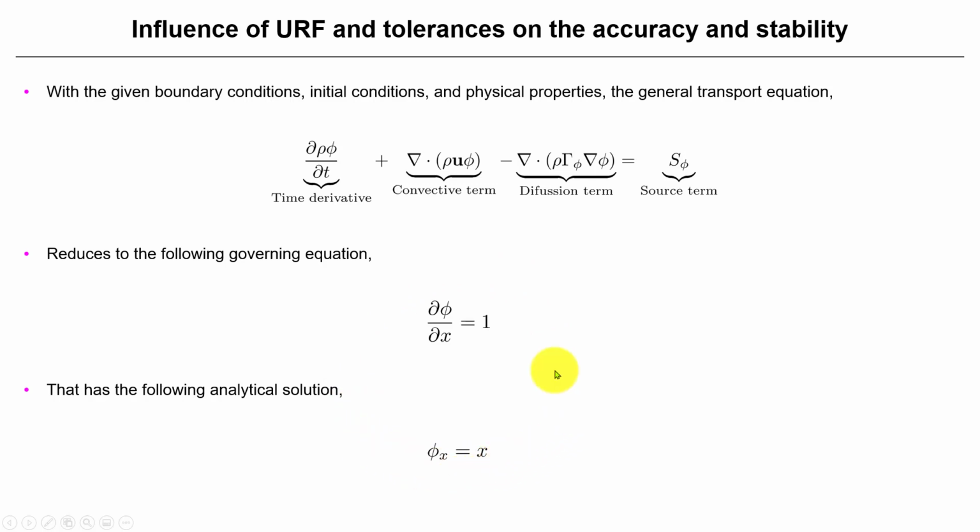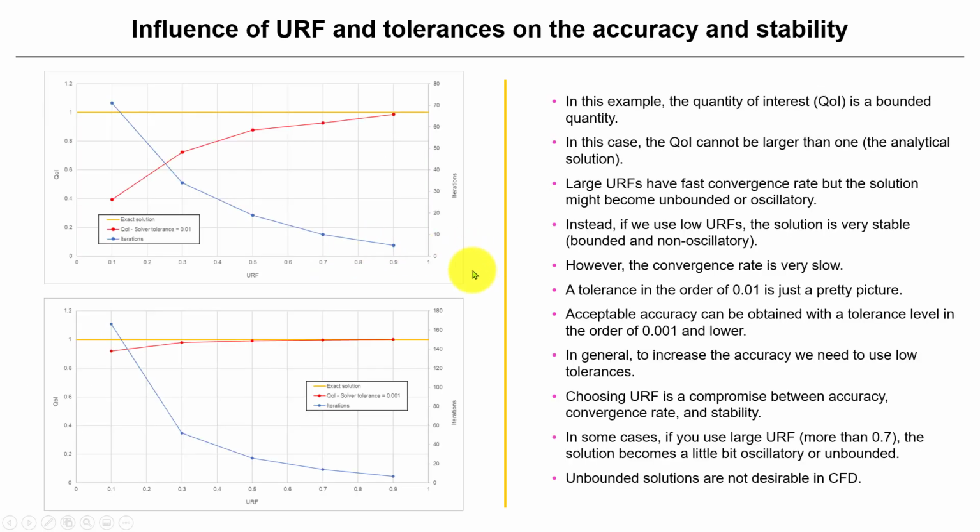Here we're eliminating the time derivative. Remember, this is a huge approximation that we use in CFD to get fast outcomes, with results that are very questionable. However, if you follow good standard practice and you know what you are doing, you're going to get good accuracy. So the big question is: if you erase these derivatives, how do you advance the solution? Those are the under-relaxation factors, which are used to advance the solution.